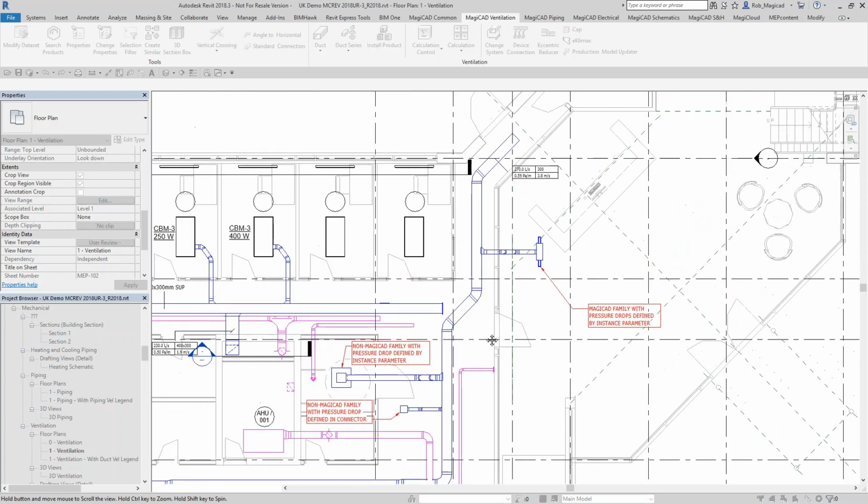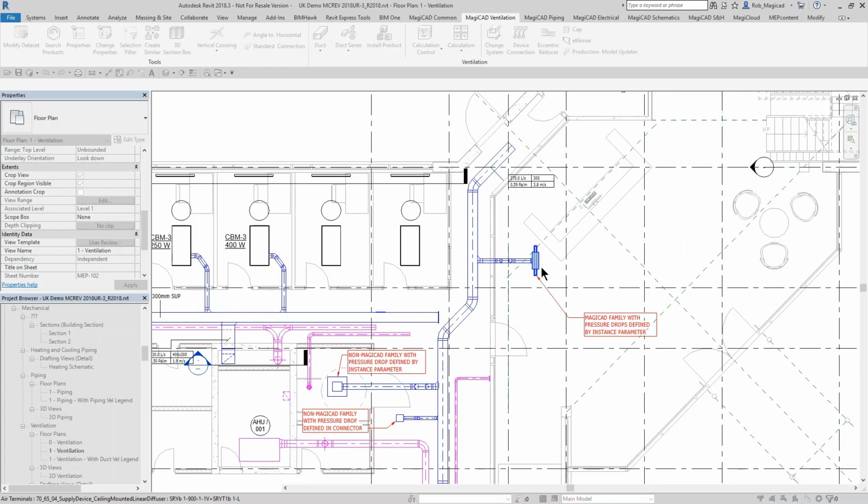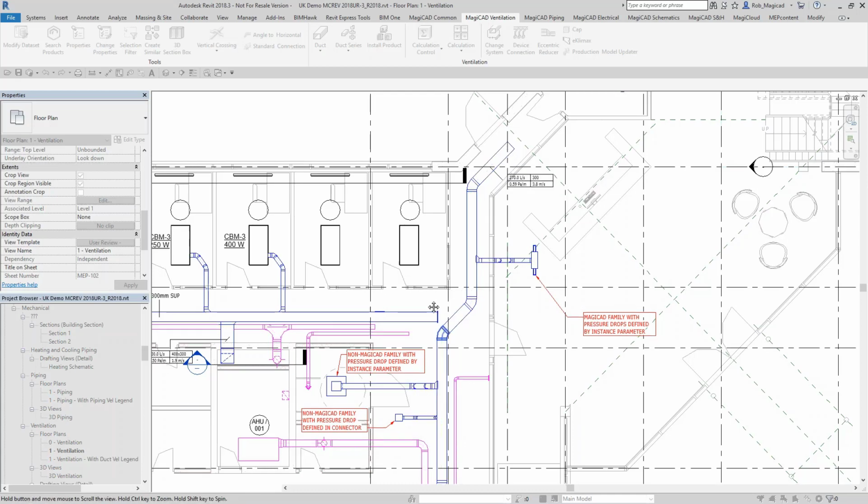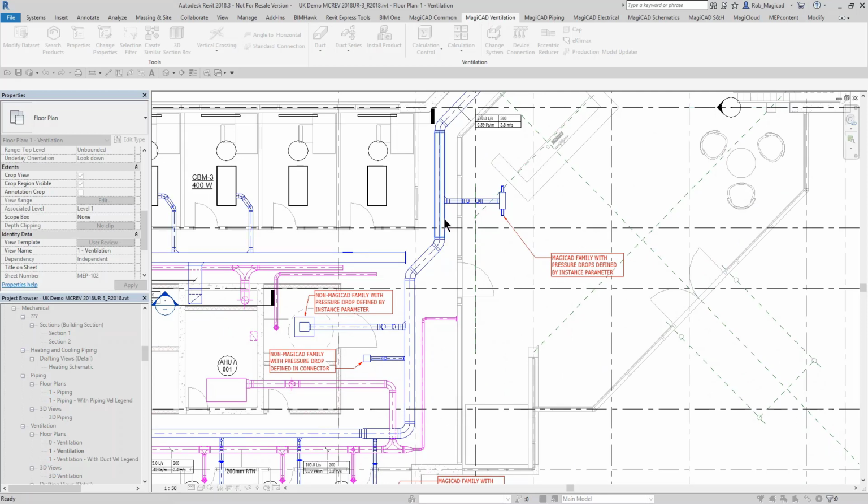So for example, if I had a 500 Pascal fan here, then this actual air terminal probably wouldn't be well balanced, because the 500 pascals will just shoot down here and obviously have a huge airflow out of this grill, but you can't control that because obviously there's no damper on it, so that would be an unbalance. But the pressure drop calculation wouldn't tell you that. It would just say I want 500 pascals. So let's look at this balancing calculation.